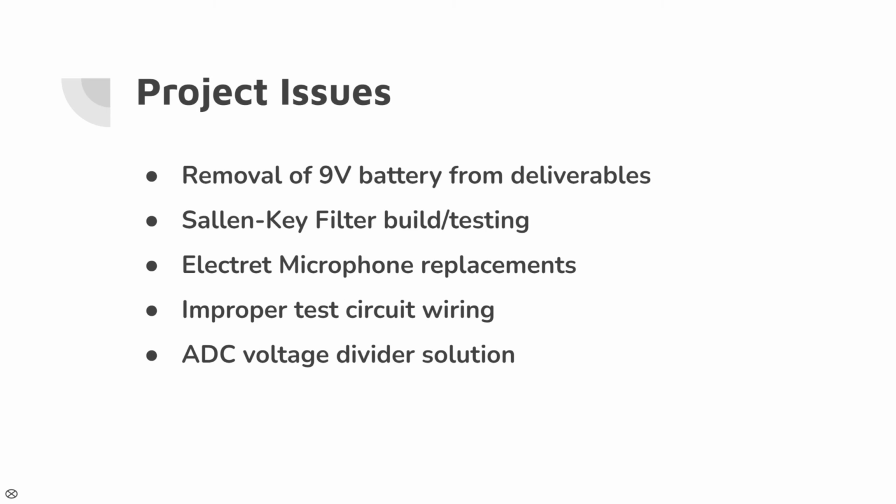And lastly, ADC voltage divider solution. With this, we were having a hard time reading voltage at the ADC pin consistently or even at all at times. But once we did a little bit of research and discovered we could set up a voltage divider at the pin, we were getting way more consistent results, and we're actually able to move on to the software portion of our project.